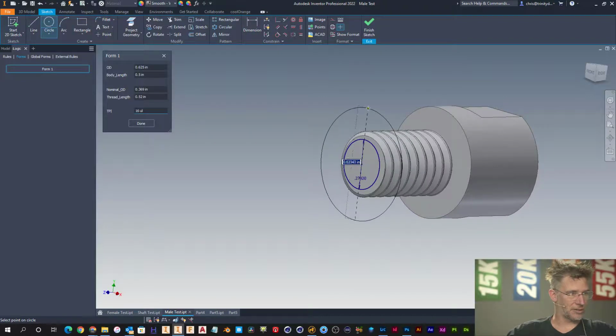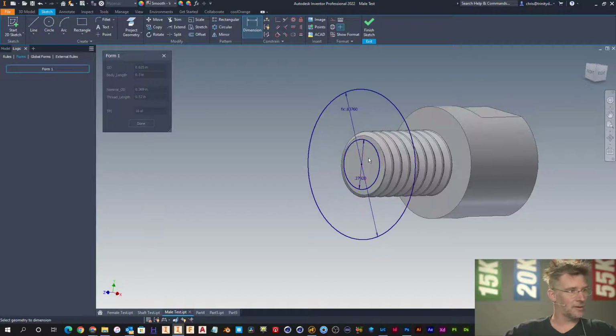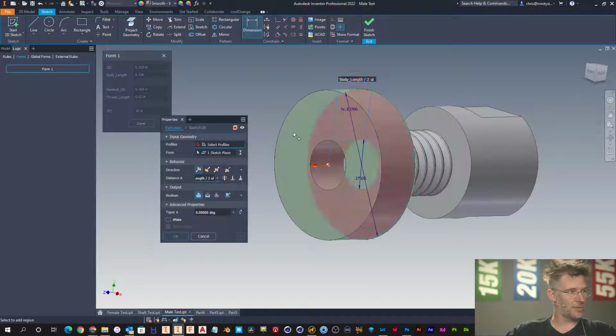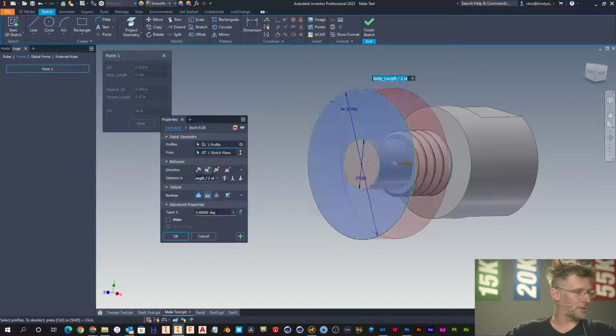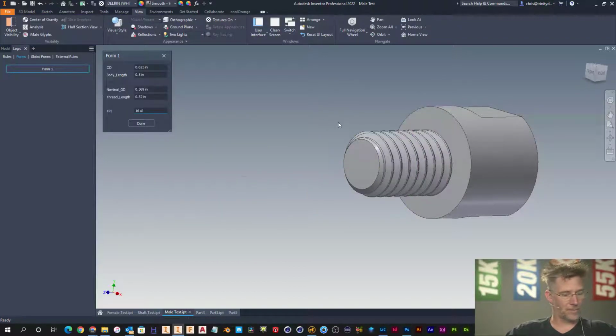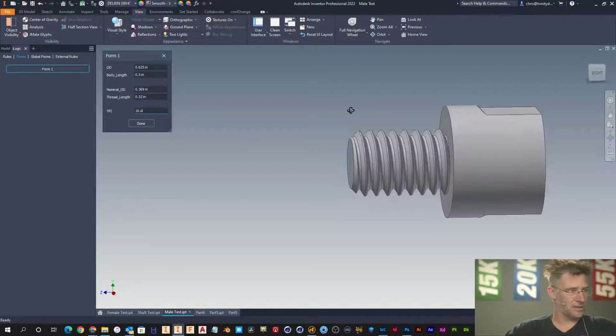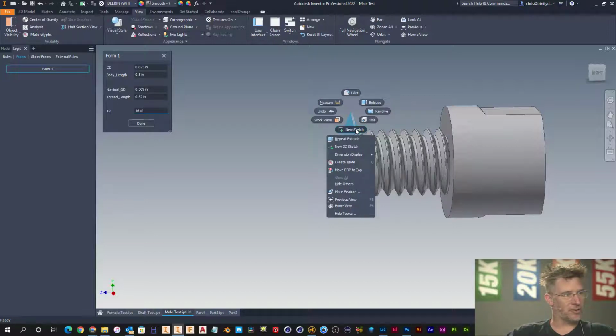Works when you use 60 degrees. And we'll just do this one. We'll go this number times 3. There we go. And we're going to subtract that, -45. There we go. And then we'll go ahead and perform our relief cut. So now we're getting to a more automated process here. So let's try to do our relief cut.